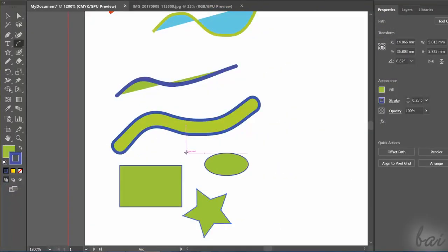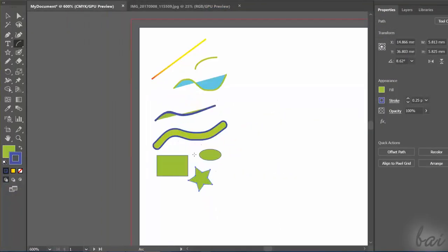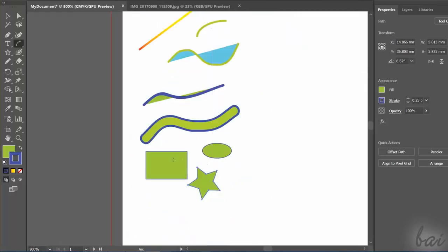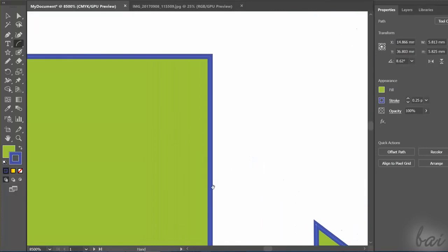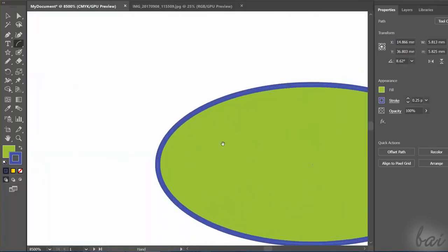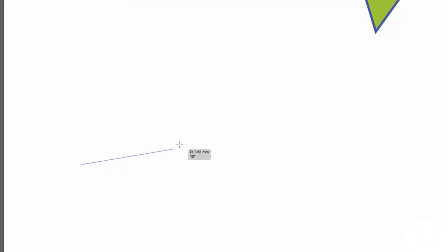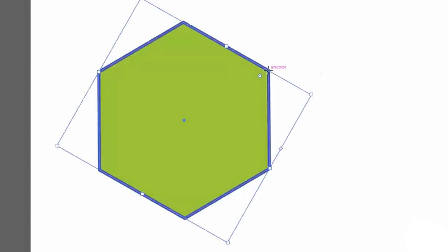You can zoom in and out around your pointer by holding Alt down and using your mouse wheel. To pan and move around, hold the spacebar key and click and drag. Illustrator has several drawing aids to help you with your drawing. While drawing lines and regular shapes, a gray dialog box shows its length and its inclination, or its width and height, depending on the shape.